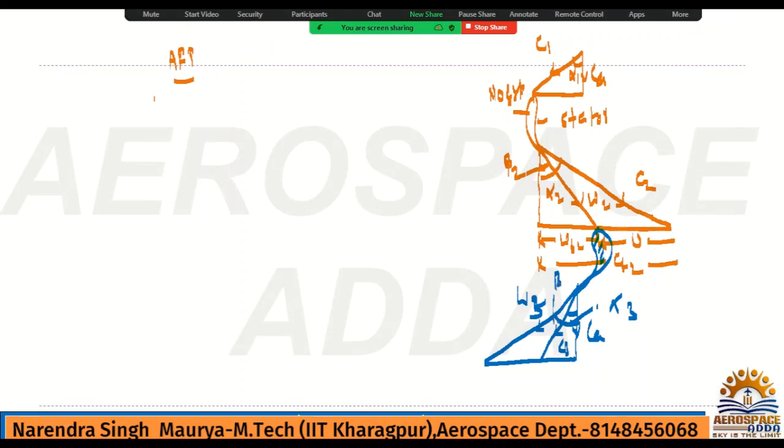So from the axial this angle will be alpha 3, and this whole angle will be beta 3. I told you relative velocity from axial will be beta, and absolute velocity from axial will be alpha. So numbering you need to take care. This is 2, this is from here, this is 1, this is 2, and again one more blade came, so after this 3.